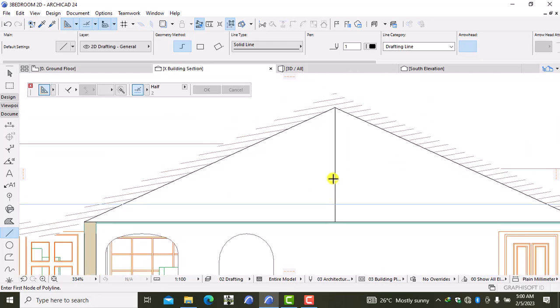So next thing I want to do, I want to take this and then Control D, drag this side at a distance of 50, enter, then Control D, and then drag it to the opposite side, maintaining an angle of 120 at a distance of 100.